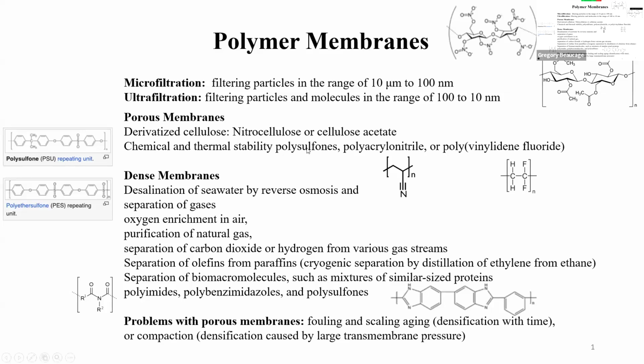Anyway, so we got that business. These are some of the polymers, because you're going to have stress on the thing, so you want really strong polymers, and sometimes, depending on what you want to separate, the polarity of the side groups matters. So this is polysulfone. It's anything that's got aromatics in the main ring, stiff polymers that are going to have high modulus.